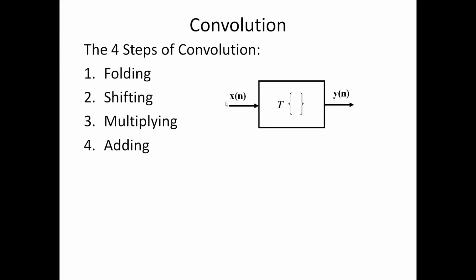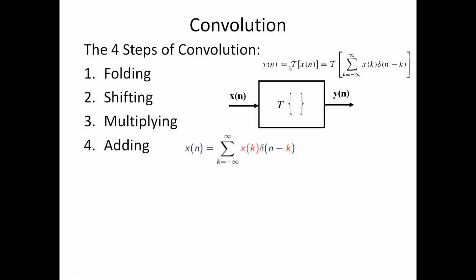And if this is a black box where you have a signal x[n] coming and output y[n] going, so this is the equation of x[n]. Here, x[n] is a combination of different unit impulses, that is delta[n minus k] multiplied by the coefficient value x[k]. And y[n] is output, and this is the transfer function here. So this can be written in this format, where h[k] is the impulse response of this particular thing. When input is delta, whatever is the response, when x[n] is equal to delta[n], then y[n] is equal to h[n]. So that is your impulse response.